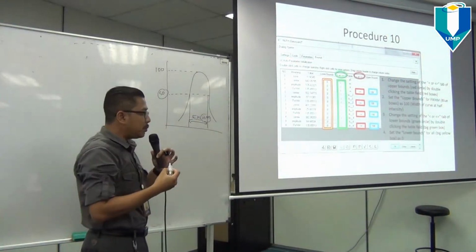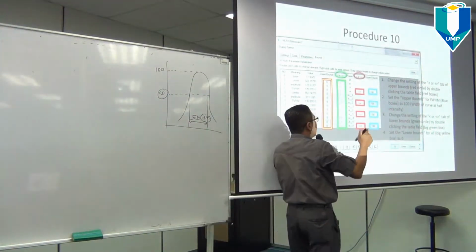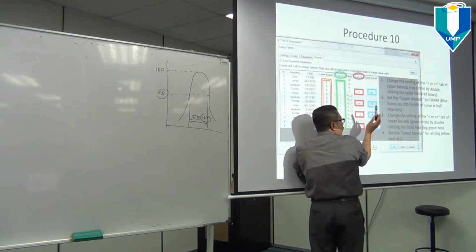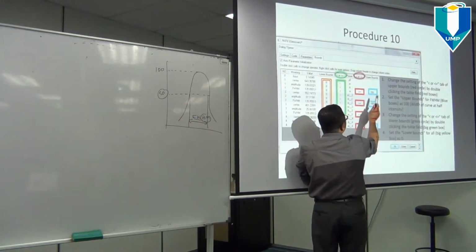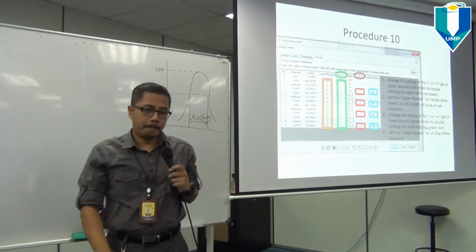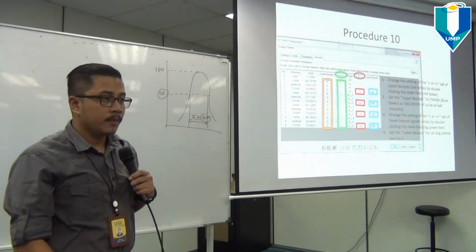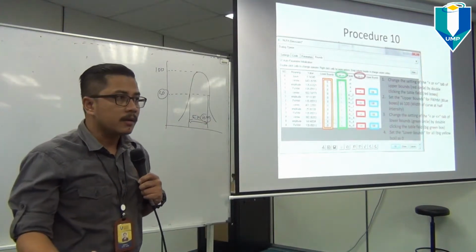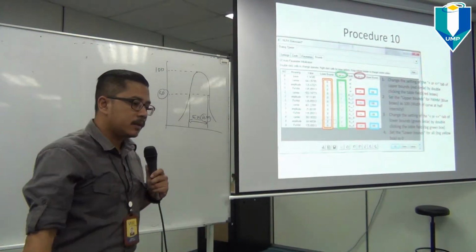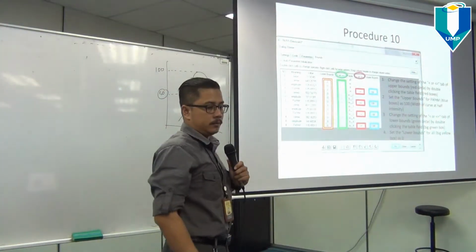So usually we will set the FWHM equal to or smaller than 100. So put the value 100 here in the upper bound. It could be another figure. We try with 100 first. Let's see whether we can get the fitting correctly.